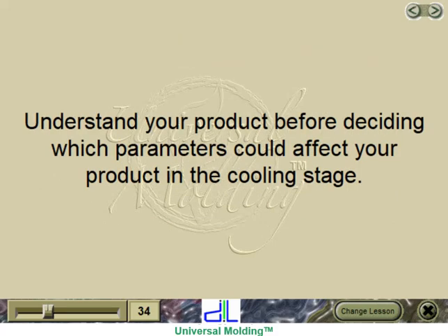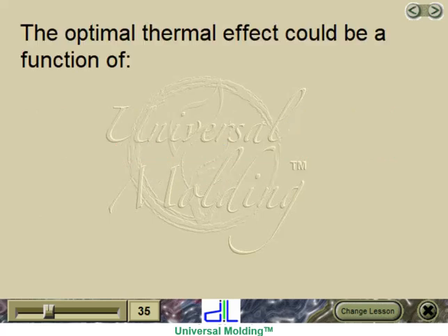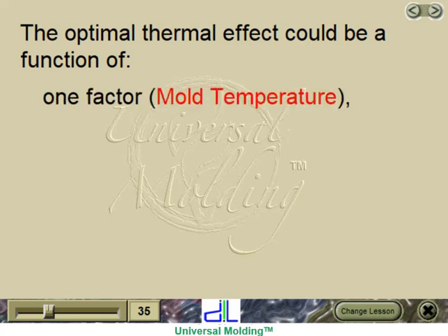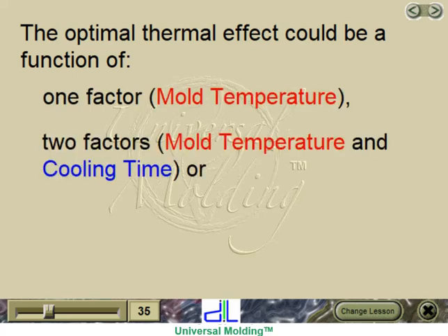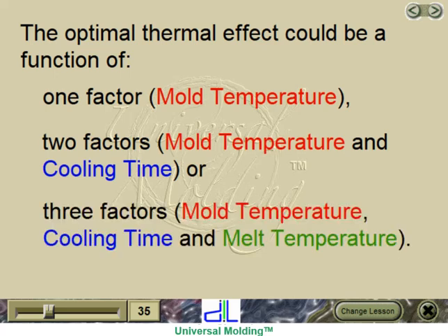Understand your product before deciding which parameters could affect your product in the cooling stage. The optimal thermal effect could be a function of 1 factor, mold temperature; 2 factors, mold temperature and cooling time; or 3 factors, mold temperature, cooling time, and melt temperature.